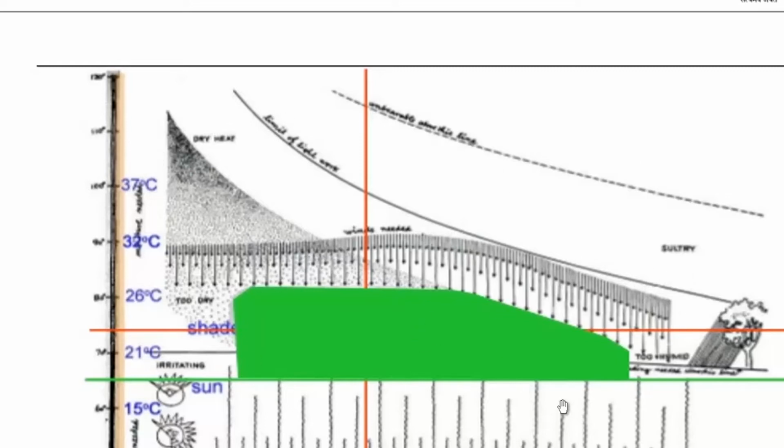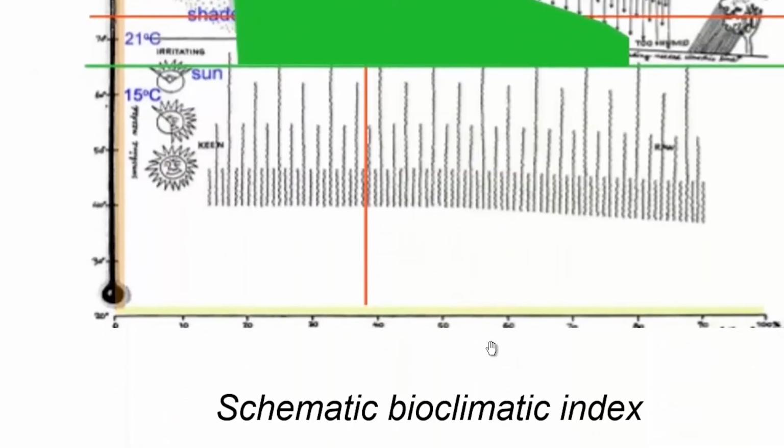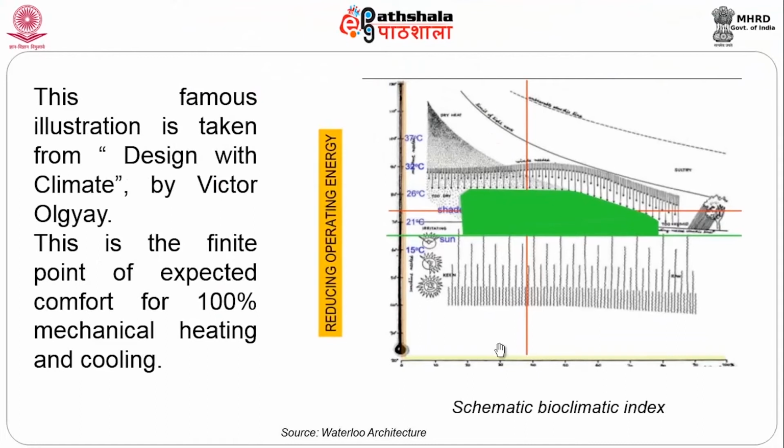And this belt is considered our comfort zone, anywhere from 21 to 26 degrees C, 28 degrees C actually, depending again on that climatic zone. Our humidity again, up to 60%, up to 70% is considered a part of a comfortable humidity that we can constantly bear.